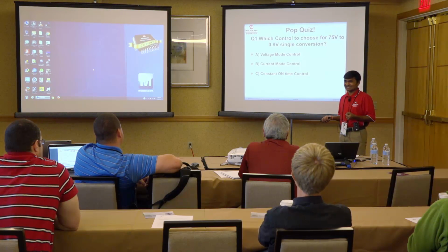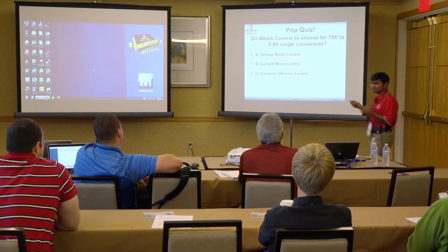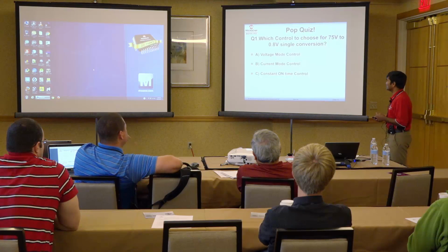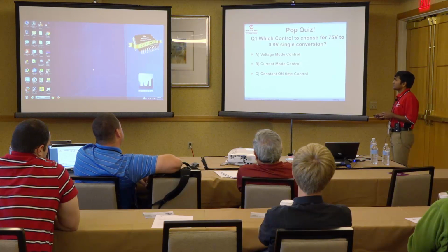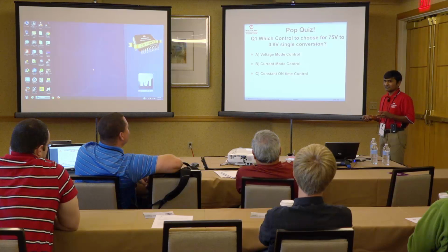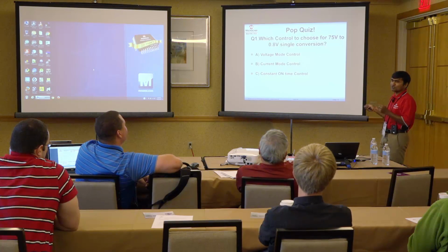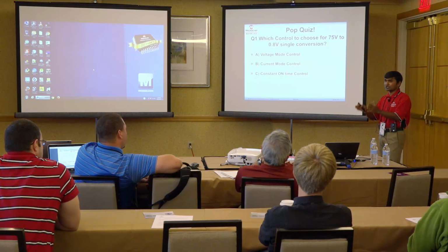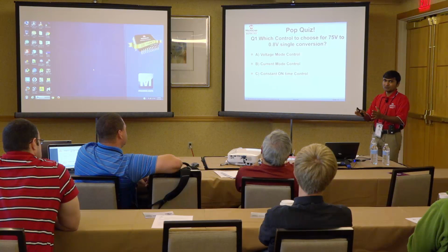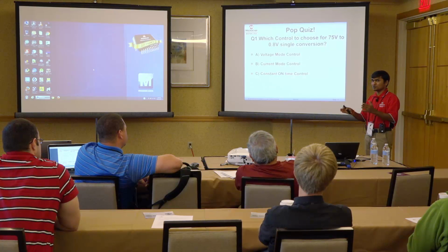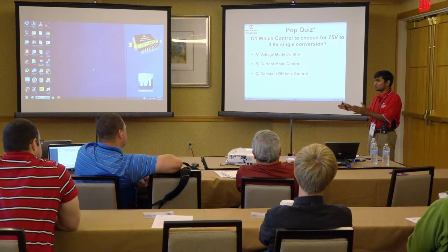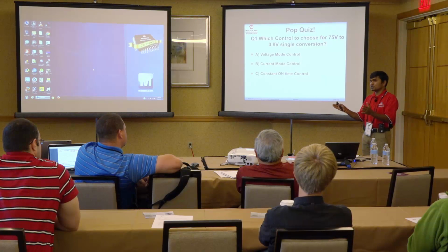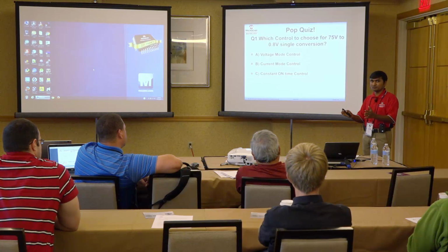Probably not B. Yes, it is not B because of the delays in the current sense loop. Yes, you are right, current mode control we cannot choose. Even if we choose the voltage mode control, from lot to lot the minimum controllable on time varies. So, if you choose the voltage mode control, one IC may regulate 75 volts to 0.8 volt based on its minimum on time, but in the future it may not be able to regulate because it reaches the minimum on time.